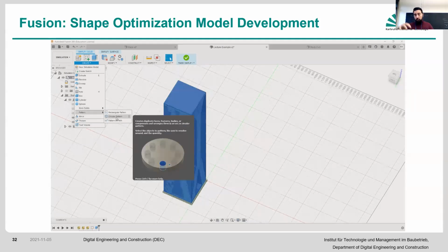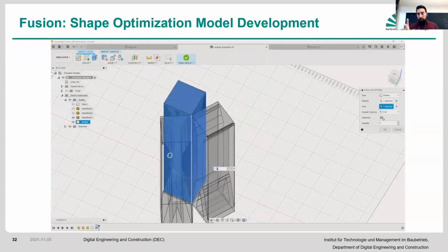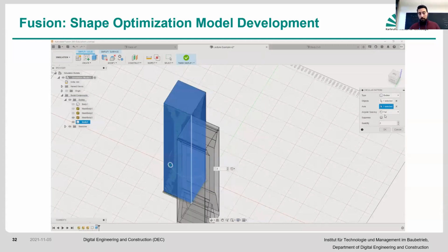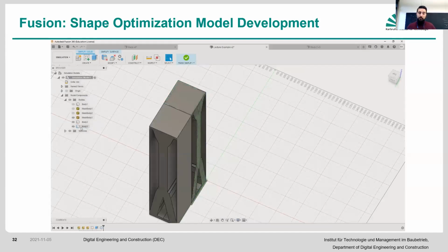So I want to create a duplicate of this, but just in 90 degrees. So we go and we find where we have to do this. It asks us with what axes we want to do it with, the orthogonal axes. We want to only do 2 in quantity, and I want to do an angle of only 90 degrees. So this is what we call a polar array. It's very, very famous. And then what ends up happening is that whatever we have here rotates 90 degrees about that particular axis that we've defined. So now we have this exact object, but on the other side.